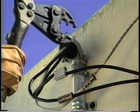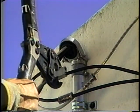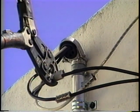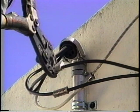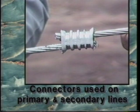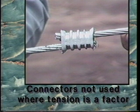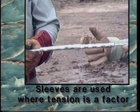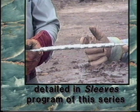Connectors are installed anywhere two electrical conductors need to be joined together. A properly installed connector will provide a low-resistance joint. Connectors are used on primary and secondary lines, including service drops. Connectors are not to be used where tension is a factor. Sleeves are used where tension is a factor and detailed in the sleeves program of this series.